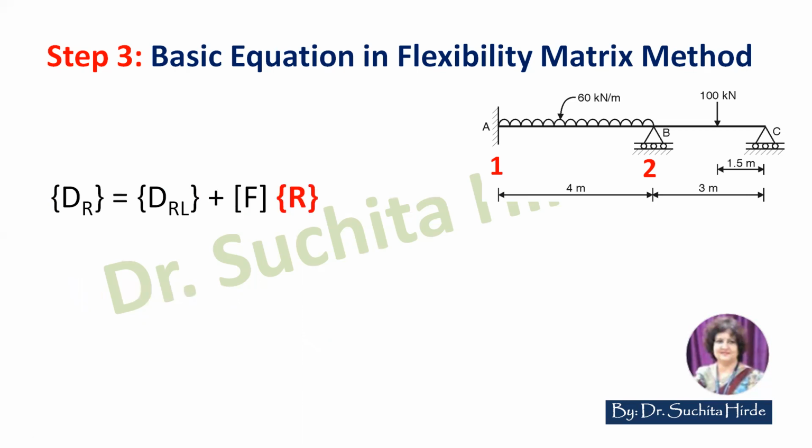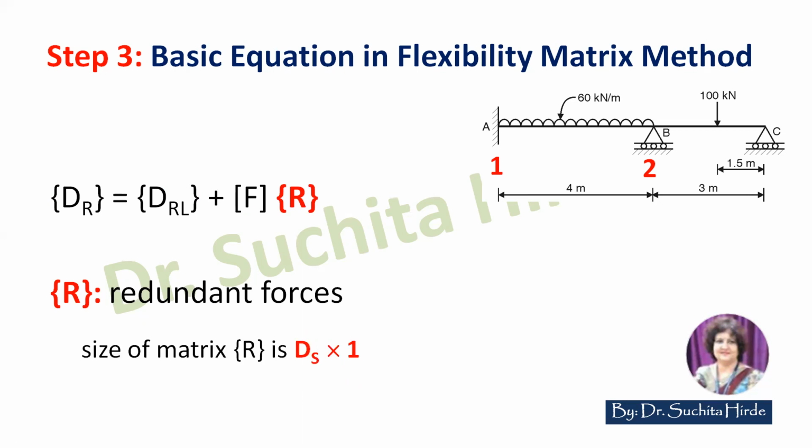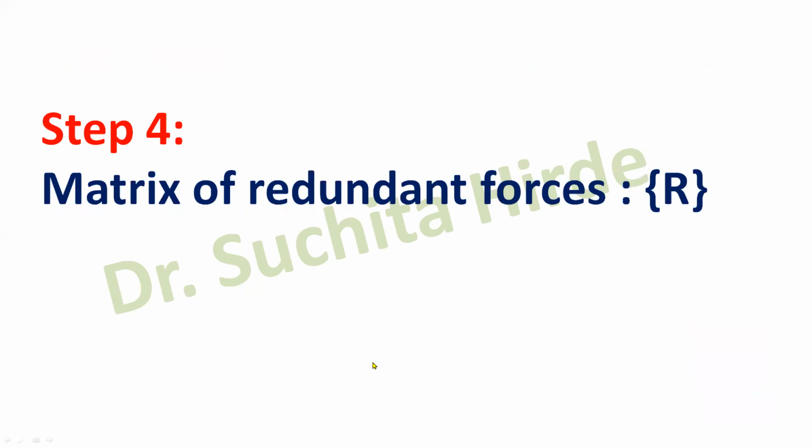The last one is R matrix, which is redundant forces. Now here we are considering MA and MB as redundant forces. So here the size of this matrix is ds by 1, which is 2 by 1. Now next step is we will generate all these matrices.